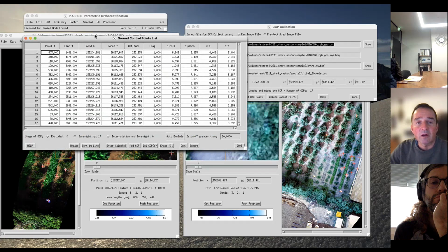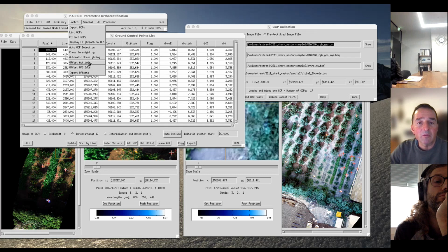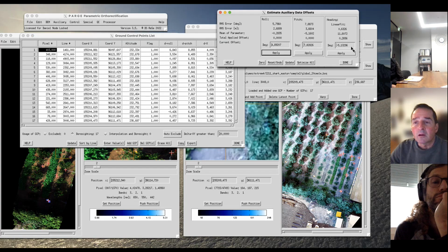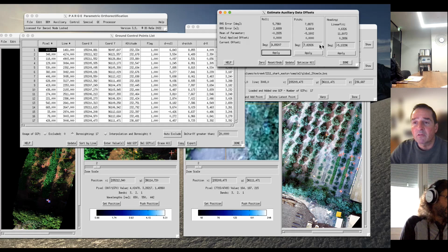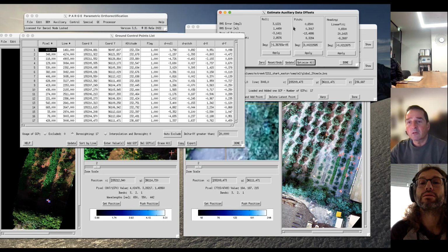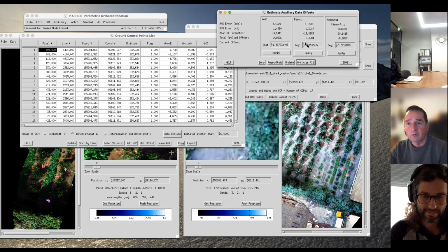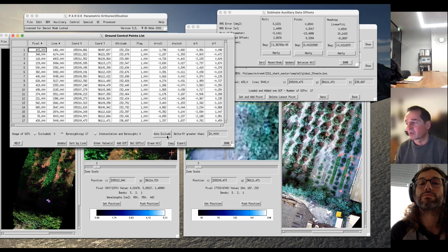So one can now try to do an optimization, and I'm doing an offset attitude and offset GPS. So I'm doing it manually here. You see the angular difference. It's 4 degrees for the roll, 7 degrees for the pitch, and 5 degrees for the heading. So I'm optimizing these 3 parameters, optimize all, maybe push it twice. Then I get an updated parameter. It's still not very nice. So what's wrong?